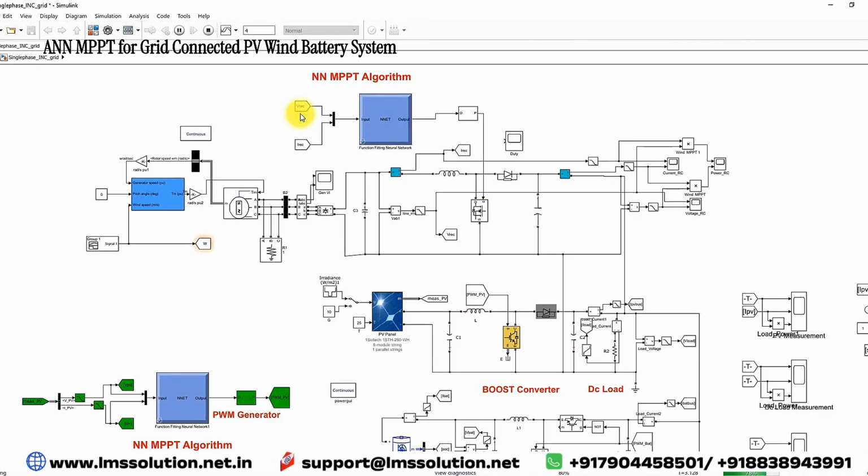This neural network receives two inputs: the rectifier voltage and the rectifier current. That means here we have to measure the current of the rectifier, and here we are measuring the voltage of the rectifier. That is given to the neural network MPPT control. It will generate a duty cycle based upon this rectifier voltage and current. This is processed via the pulse generator, and the pulse generator's switching pulse is going to control this MOSFET to extract the maximum power from this wind energy system.